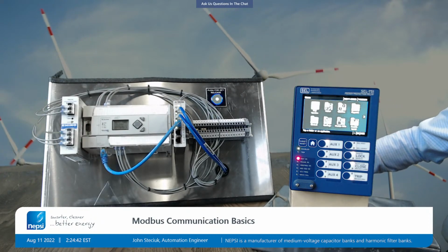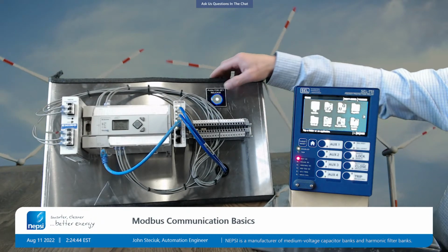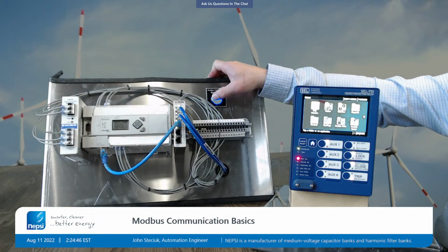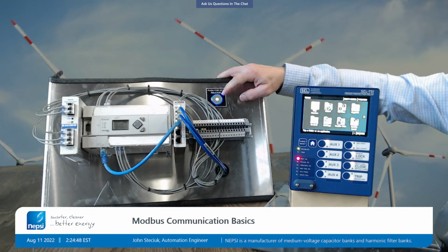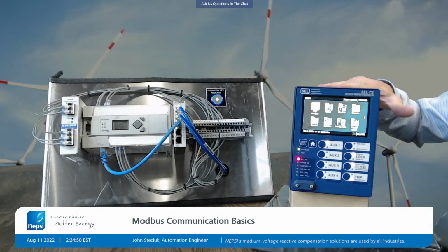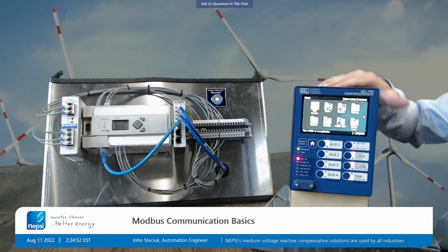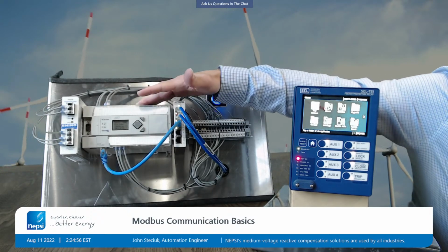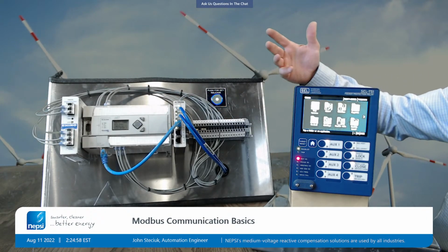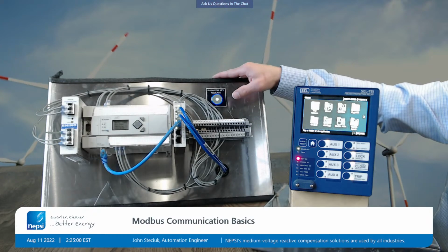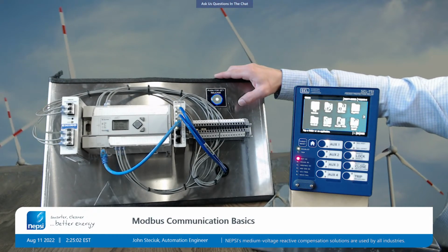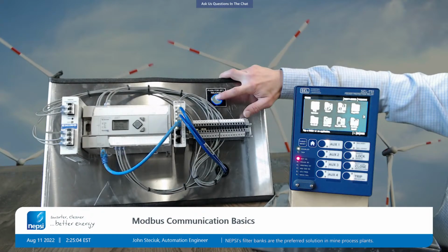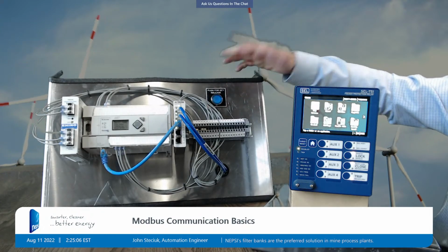And likewise, we're going to write data from this PLC to the SEL751 to reset. So we're taking this contact from this push button to an input in the PLC, sending that via Modbus to change the status of remote bit 01, and that works good.